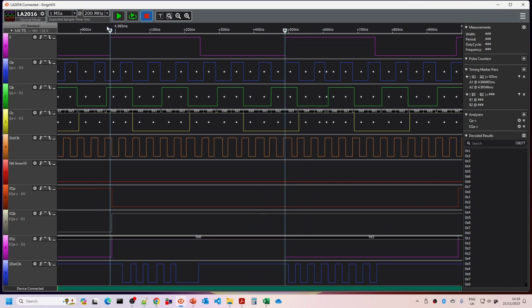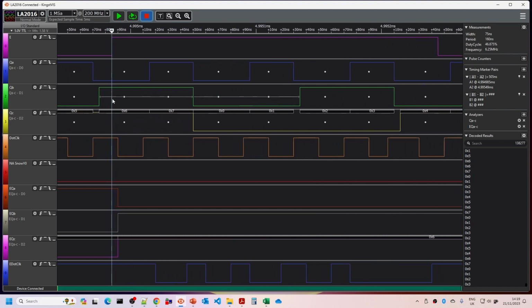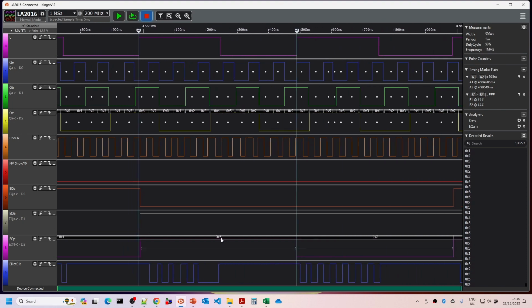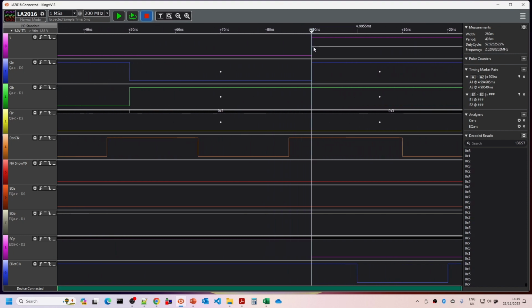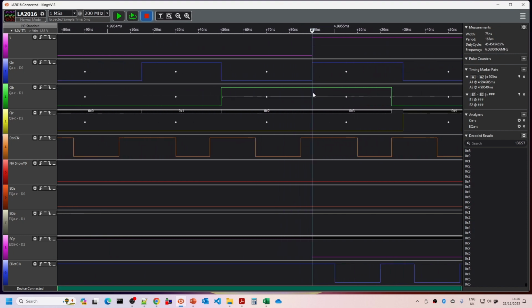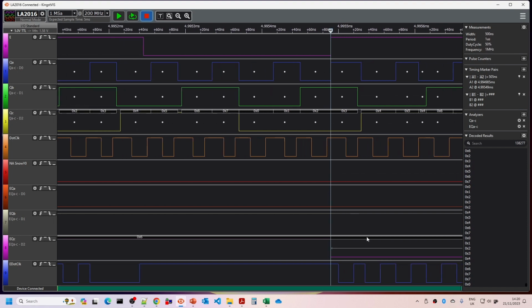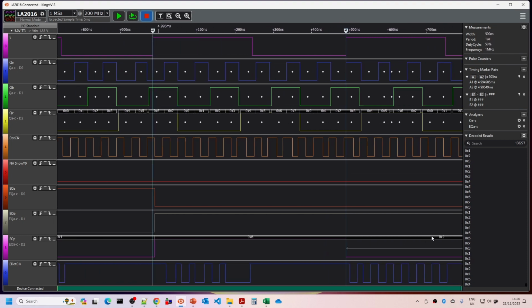These are the rising parts of the E signal, and if we go in here and look at that point in time, the QABC signals are resulting in 6, 0, 6, and then if we look down the bottom here, what value is being latched here? Yep, we've got 6. And then if we go up here, this signal is right on the boundary, in fact, between 2 and 3, and generally I think when something's right on the boundary, it's probably going to take the value to the left of the boundary. So that's right on the transition. If we look down the bottom, we will see that the value down here is in fact 2.